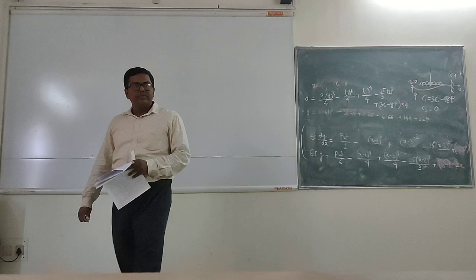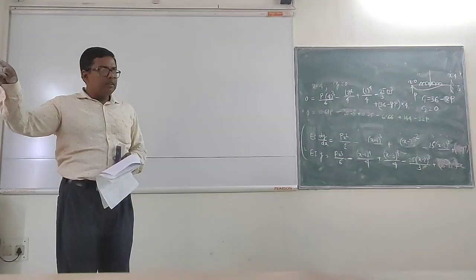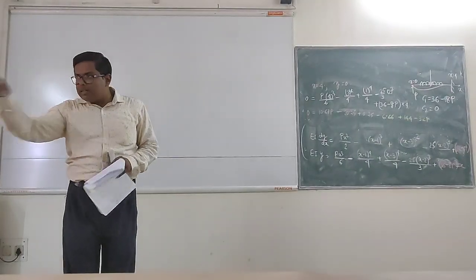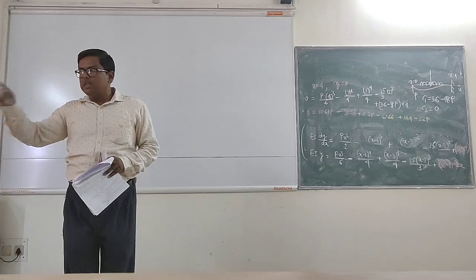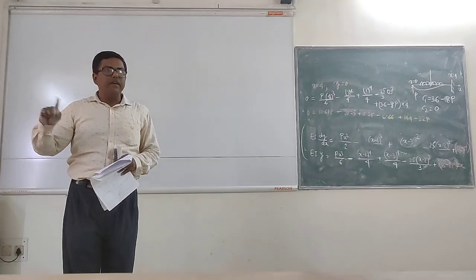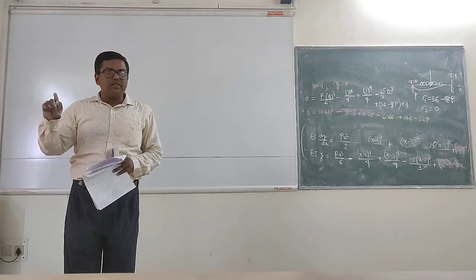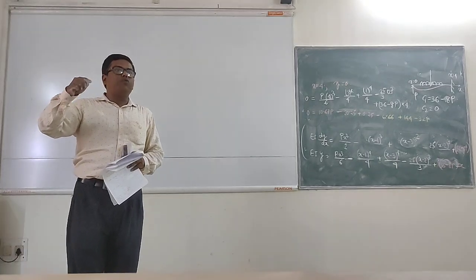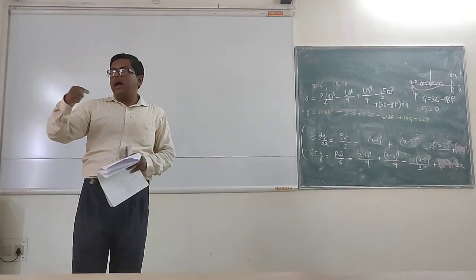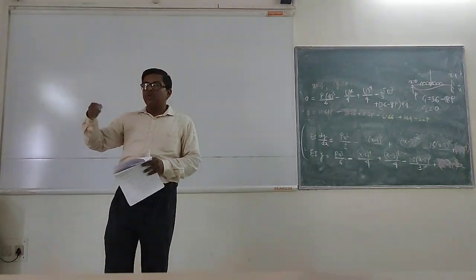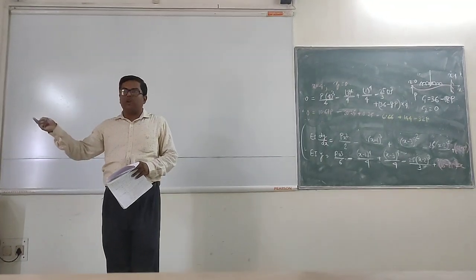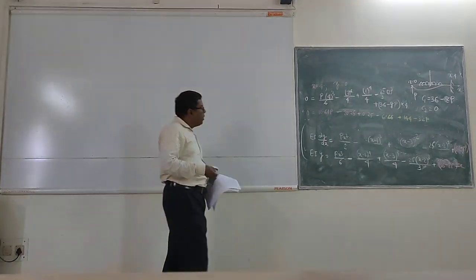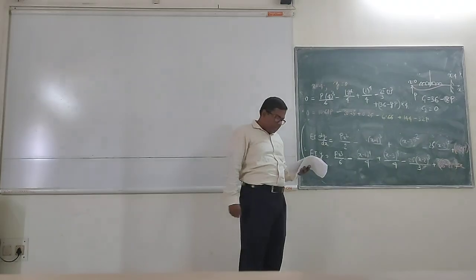Clear? All of you are with me? We are doing simple algebraic equation solving, just calculating the value of P. Putting back the value of x, considering the third boundary condition at x equal to 4, the deflection value at the built-in end or the fixed end will be equal to 0. That's all. Okay? So now if I do it, what will be the condition? You tell me.